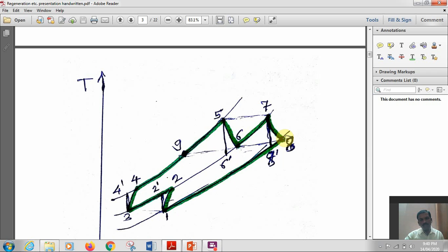Now you know this formula. Then for ideal, T5 is equal to T7, T6 is equal to T8. Everything is known; now all the temperatures are known. For ideal regeneration, T9 is equal to T8. Now I will conclude in a single line, and then we will see the step-by-step calculation procedure of the solution.